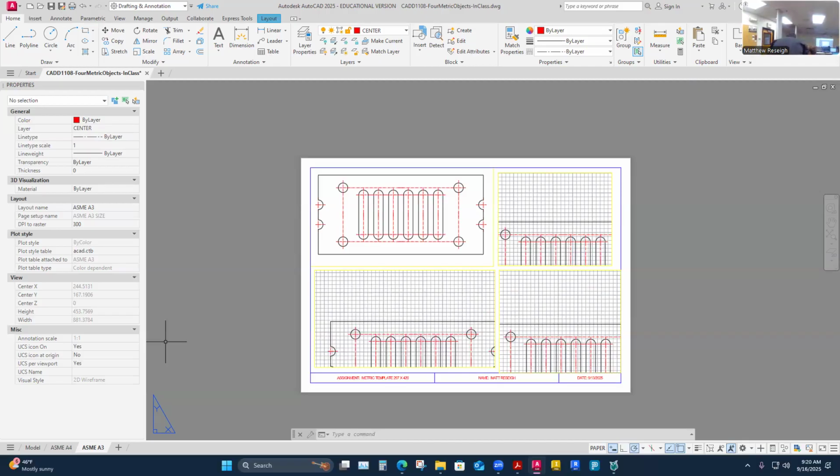Maybe try it again. Fillet radius is 0. Did we hit enter? It's supposed to be 3. Right, 3 radius. So do your fillet again, and then do the distance next. You can do radius, and then 3, enter. Now it wants to select the first object, and then the next one. I don't think it loves that. How'd you do yours, Candy? Were you able to do that?